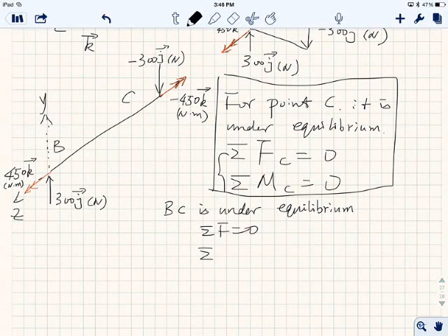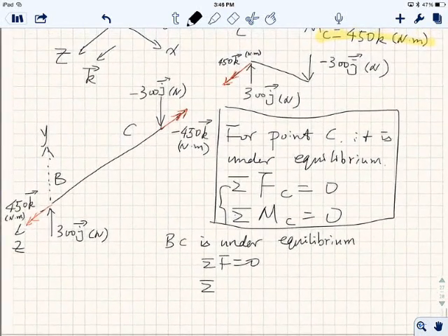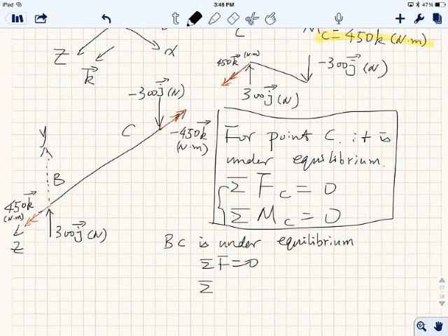Now there's one thing I need to mention here. First of all, let's see this. Remember we learned the concept of torque, right? So this is easy to understand. Everything's on the bending. So this moment, the direction of the moment is 90 degrees to the beam. See this? This double arrow, the red one, is 90 degrees to the physical beam over here, right? While in this case, this BC, the moment, the double arrow, the red one, is in the same direction as the beam, right? Now, do you know what kind of deformation this moment is going to cause?